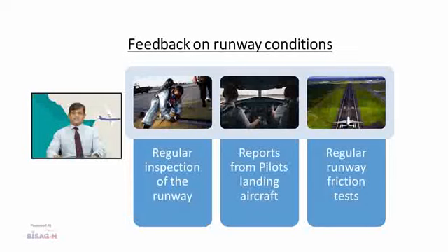To get the best results out of the best practices being adopted in runway maintenance, regular feedback on runway condition cannot be overstated. And while regular testing and inspection of the runways must be a periodic feature, taking reports from pilots who operate the aircraft can go a long way in mitigation of the runway excursions.